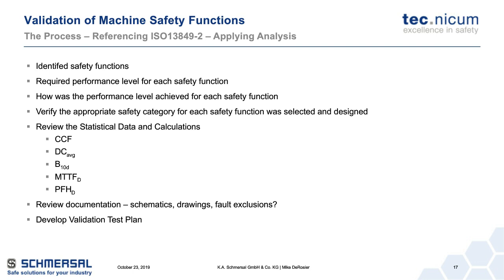We're not just talking electrical. Even though this example is electrical, because we're just shutting down a three-phase motor, that's the safety function by opening up a door, shutting down that three-phase motor. However, maybe you have hydraulics, pneumatics. What are you doing there? Did you start looking at the designs of that? What safety levels do they need to be? Don't just stop at the wire.